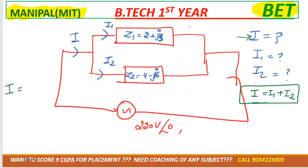How? Total current must be equal to the total voltage divided by the total impedance, right? So total voltage is how much? 220 angle 0. Impedance is denoted by Z and total impedance we can denote by ZT.